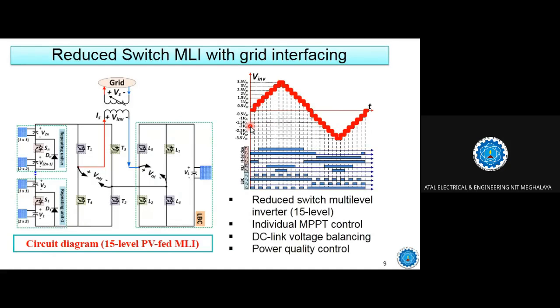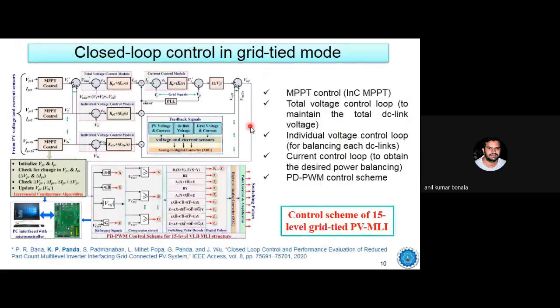Yeah. So these are the points. Whether the regularization of voltages will limit the MPPT? No. Here I can see that the individual MPPTs are being regulated by an MPPT controller, and then it is processed to an outer voltage controller, which is supposed to be regulated. Yes, right? Here, the individual voltage control module is there.